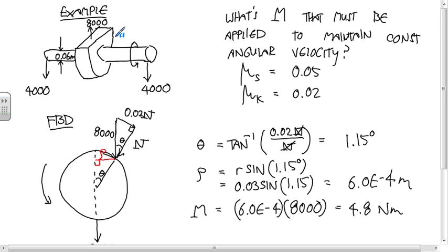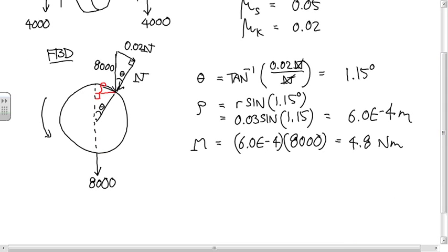Okay, what we really calculated, so the question asks what's the external torque you have to apply to keep it rotating. That's not what we calculated. We calculated the moment that's produced by that offset in the bearing, but the only two things producing a moment on this axle are an external torque that we apply and the torque due to this offset. And so whatever this is, that's what we have to apply. Do you know what I mean?